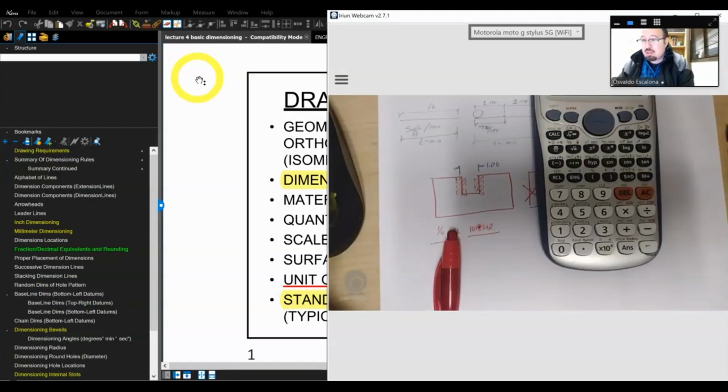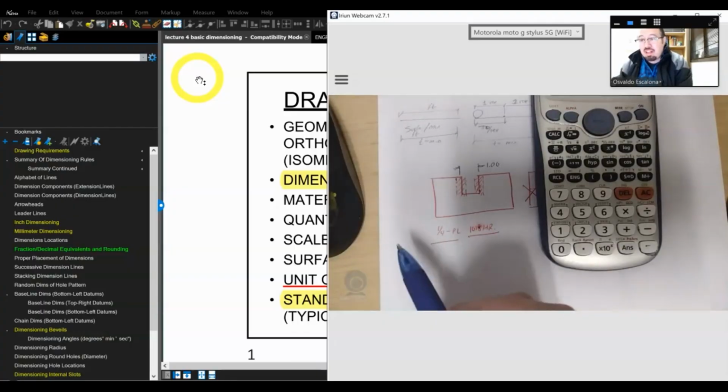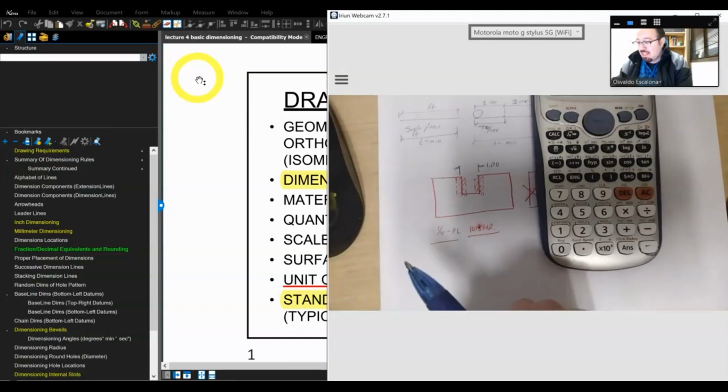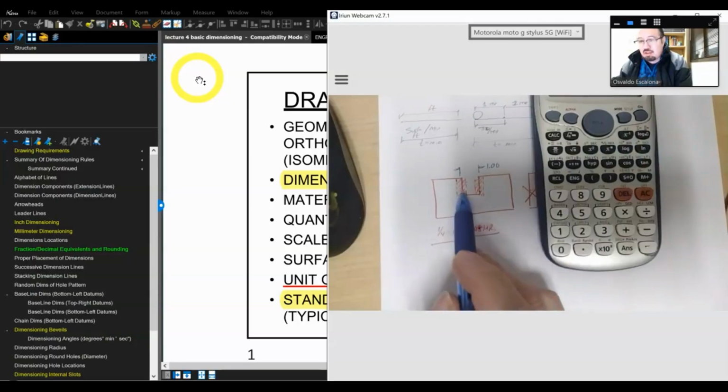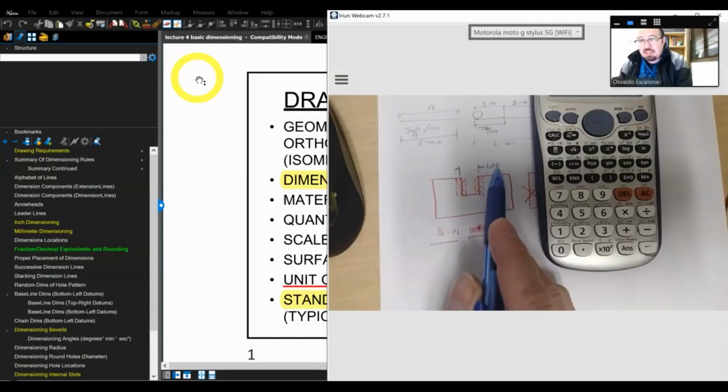Because in reality somebody needs to cut this. It's my piece of sheet metal, so I need to give it leeway for manufacturing. This wiggle room allows me to grow or decrease in size, but close to 1 inch though. The wiggle room, we call that tolerance. Every drawing should have its tolerance.